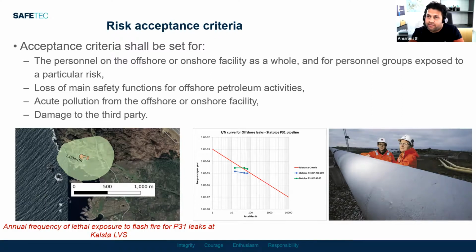So the only way of doing it is rock dumping, or we need to bury the pipeline in the areas where you have shipping fairways or more intensive trawling activities. But there's no requirement for the depth of the pipeline. There are, however, regulations relating to free spans.